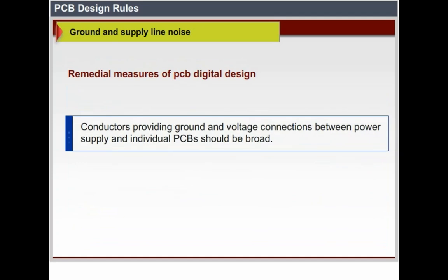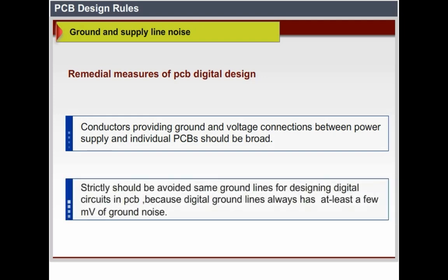Conductors which provide ground and voltage connections between the power supply and individual PCBs should be broad. Sharing the same ground lines between digital and other circuits should be strictly avoided, because digital ground lines always have at least a few millivolts of ground noise.